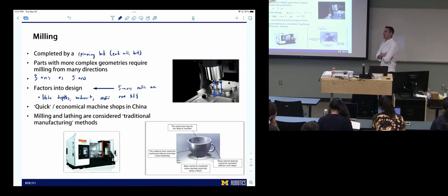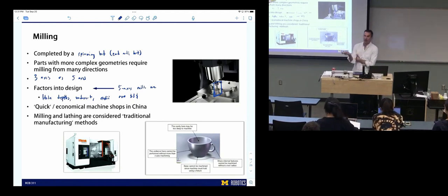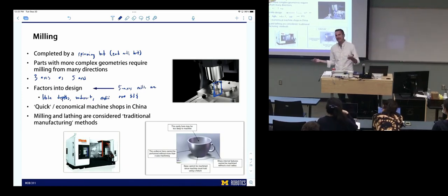many issues, like when would you want to mill something as opposed to 3D printing it? Oh, okay, yeah. So actually, we mill everything. It does have issues, but if you don't mind paying for it, it's not a big deal. So it just means that when we build parts, we barely consider these things at all. And we just already know it's going to have to be machined on a 5-axis mill. And then if you think of it that way, it doesn't really constrain you much.